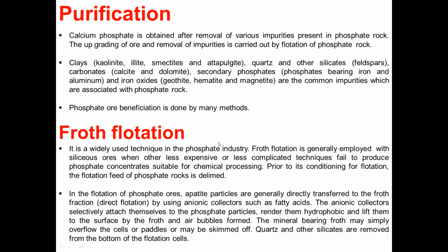It is a widely used technique in the phosphate industry. Froth flotation is generally employed with siliceous ores when other less expensive or less complicated techniques fail to produce phosphate concentrate suitable for chemical processing. Prior to its conditioning for flotation, the flotation feed of phosphate rocks is deslimed to remove the fines present in it. Then in the flotation of phosphate ores, apatite particles are generally directly transferred to the froth fraction.